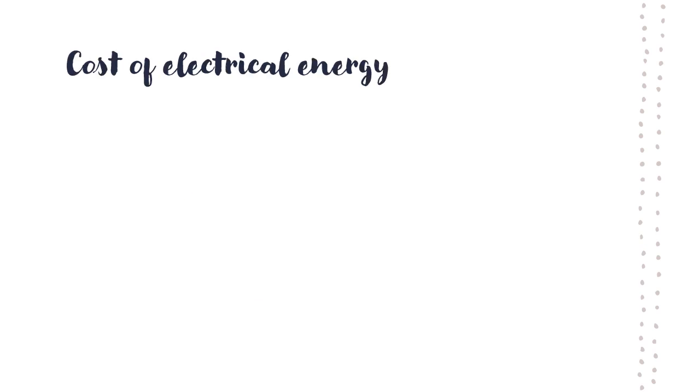And the last part we have is, how do we find the cost of the electrical energy? How do we pay for the electrical energy we have used? To find the cost of electrical energy, every energy provider will have a rate, a tariff. According to their tariff, 1 unit of electricity or 1 kilowatt hour will be somewhere between 6p and 15p on average.